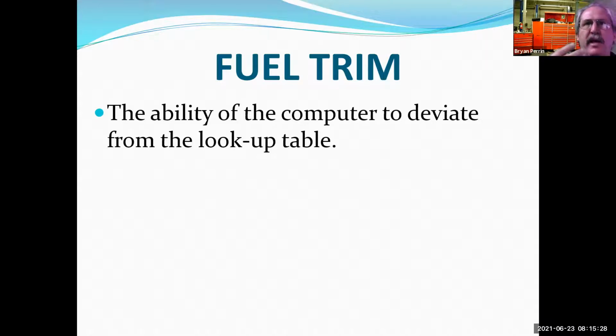So in other words, if I have a hole in my vacuum line going to my MAP sensor, it's going to detect that as more load and dump more fuel. So on cars with speed density, we normally see rich adaptation codes, 172 and 175. Where on mass airflow sensor cars, we normally see lean adaptation codes, 171 and 174. So when you have the opposite of that, if I have a mass airflow sensor car with a rich code, those are extremely hard to diagnose. If I have a speed density car with a lean code, very hard to diagnose. And that's where this comes into play.